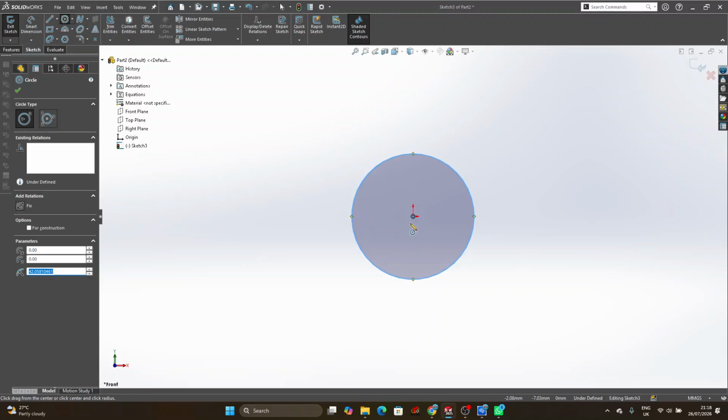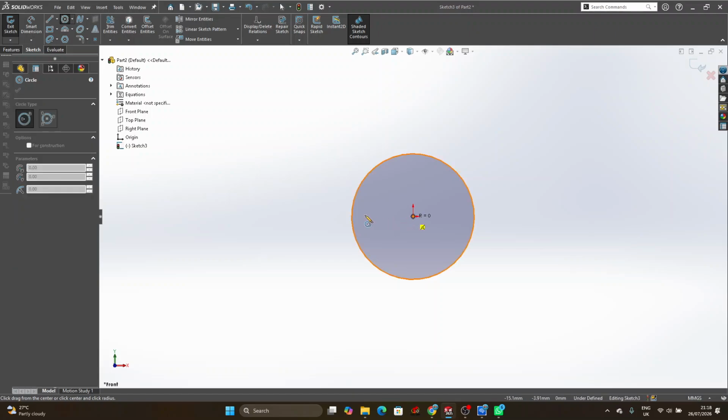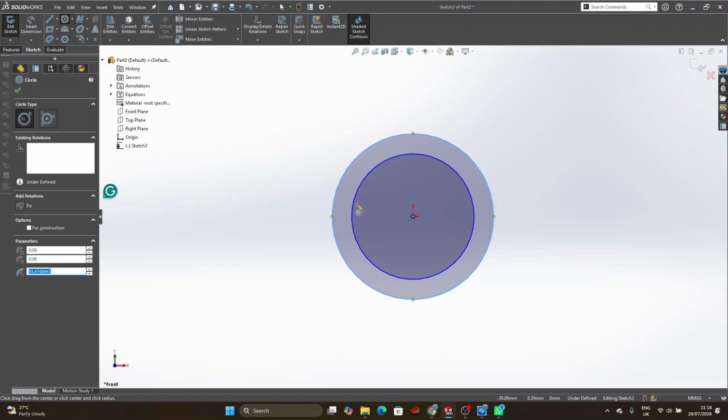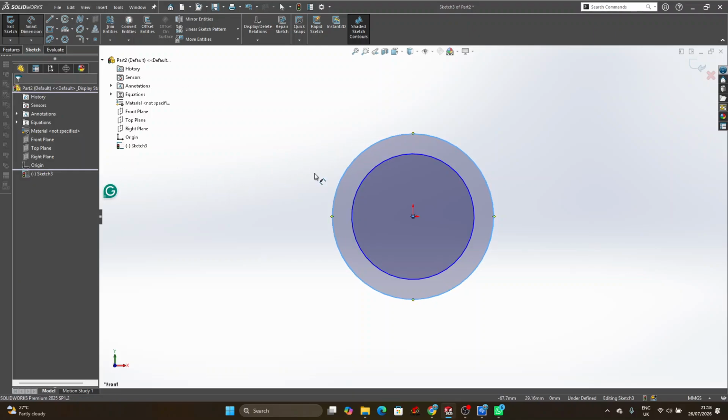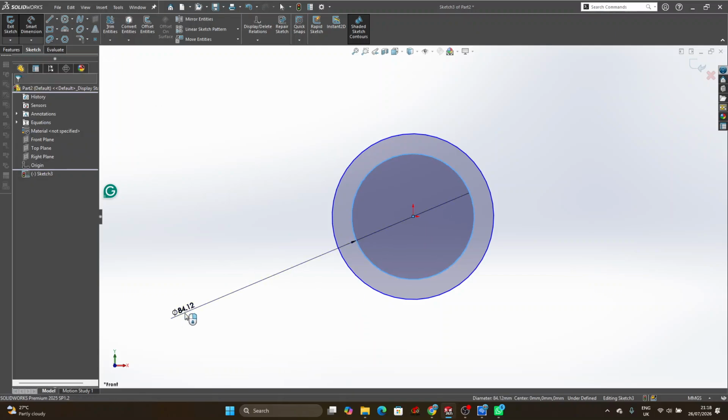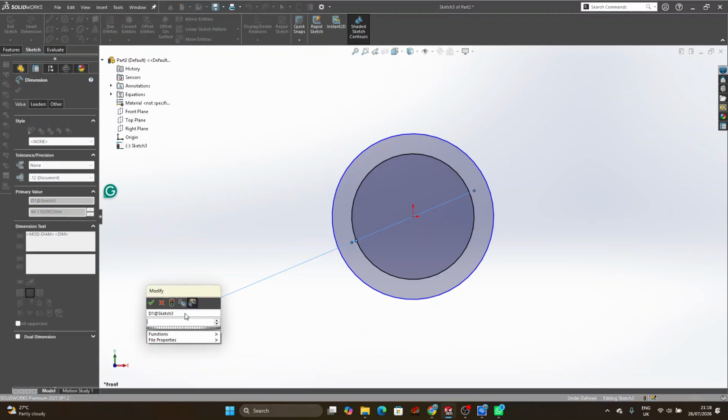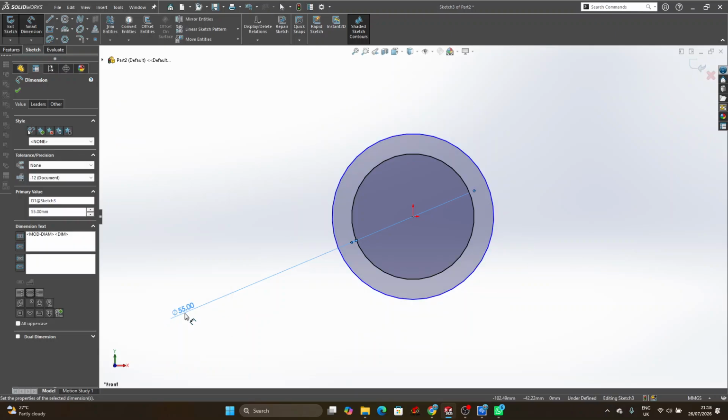I'm drawing this. I can decide to do another one too, which is the outer circle, with a radius of 45. Here they didn't give us the diameter. Normally it's supposed to be diameter, but it is radius that is being given. You can just multiply it by 2. So you can start your dimension here. Dimension the inner circle to be 27.5 times 2. Then you click on your shift key and the star there, times 2. You can also try to multiply it in your head, but if it's very difficult, just multiply it with the normal star key on your keyboard.